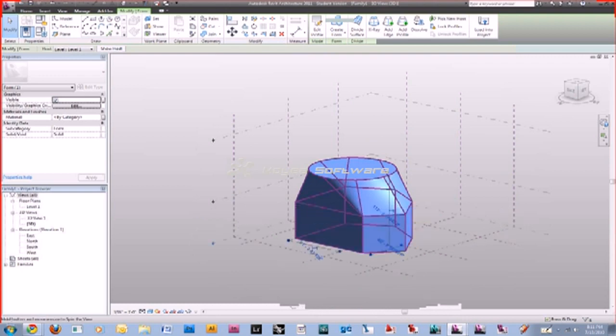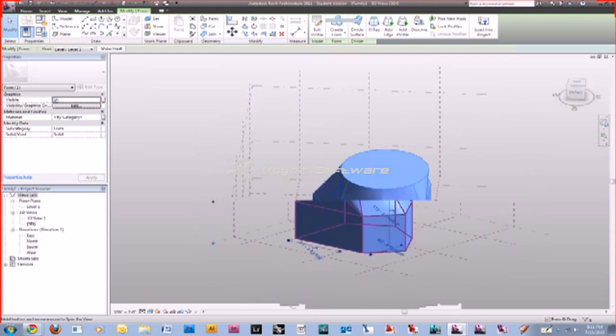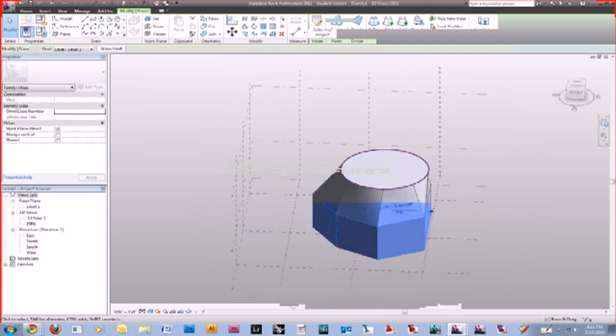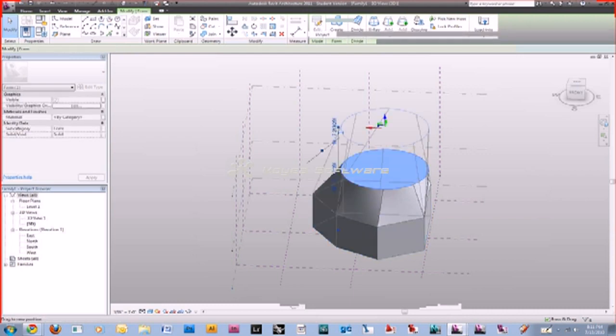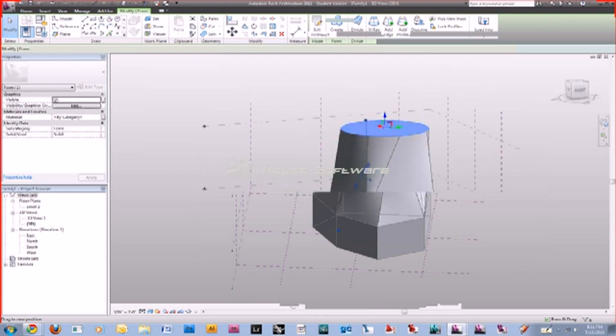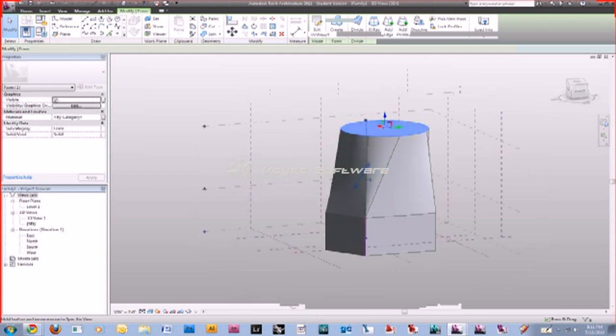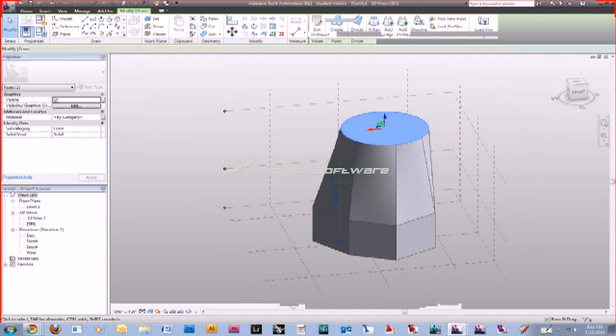And then we had a question: can you now extrude the top? And yeah, you can. You can just click the face and then start to drag it up. And that's where if you have a shape that looks like it's kind of imploding on itself, if it looks like the shape is stressed, there's not enough room for you to actually create that shape. That might not be a bad thing. You may want that in your architecture, but best practice would be to go ahead and give it a little bit of breathing room or figure out a way to make the shape a little less complex or to add surfaces in where it's actually dividing itself.